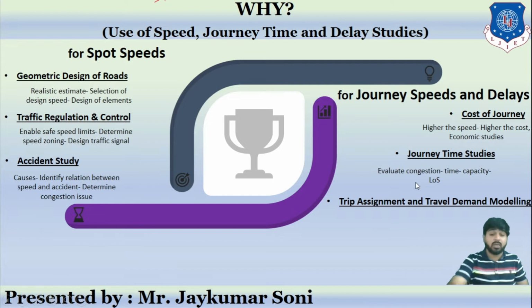Then, in order to assign the new trips, in another subject of transportation, such as urban transportation planning, that you are learning, there are 4 modules: trip generation, trip distribution, modal split, and route assignment. Means if I, as a planner, am constructing a new road, I have to know that this road will pass from this point to this point, this many vehicles will generate their trips from this point to this point, this will be the origin, this will be the destination, and these are the routes that I should provide. This is the travel demand modeling.